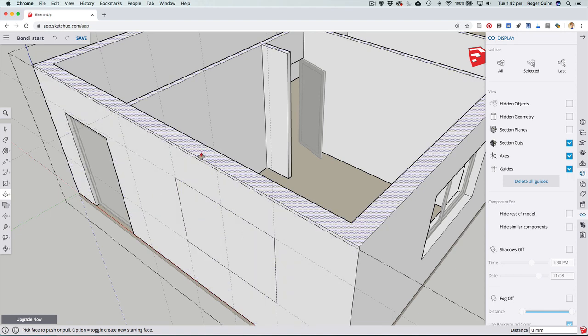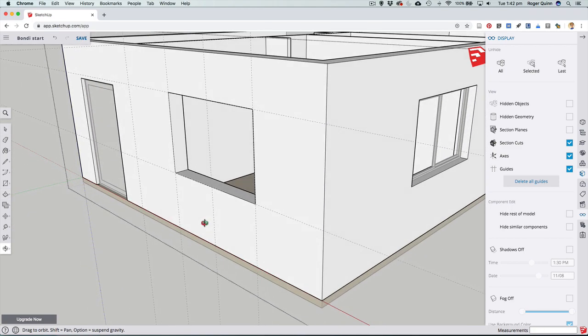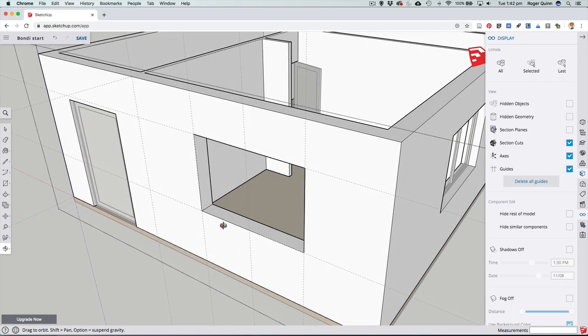So this particular wall is 230 millimeters thick. So if you just start push-pulling anywhere, type 230, and that will also knock that all the way through. Okay, so there's our cavity. All done. Now, I do not want to start making my frame directly in this group, because if I do that, it's going to interrupt, once again, the geometry that I've got on this wall. I just want to leave that as a cavity.